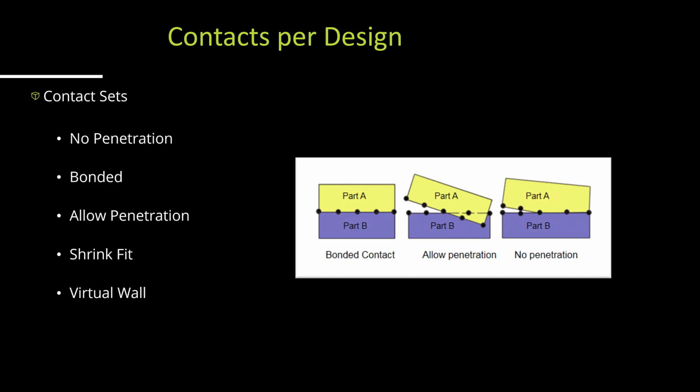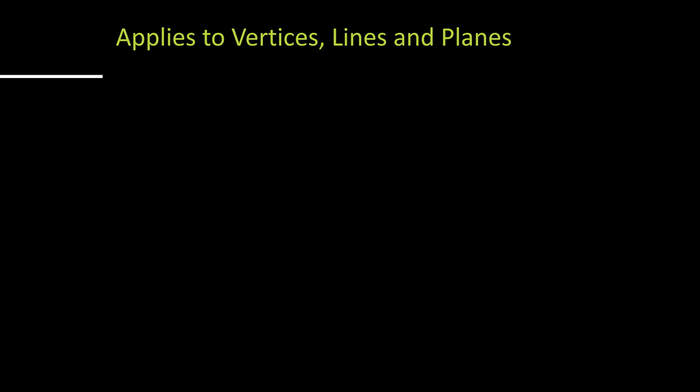That's another way we can tell SOLIDWORKS to not pass through a certain plane or area, and we have to specify how rigid this wall is. We have to specify the constants for this wall if we're going to tell it to hold this model instead of using a fixed geometry fixture, because that'll basically hold our degrees of freedom, which I'm going to segue into now.